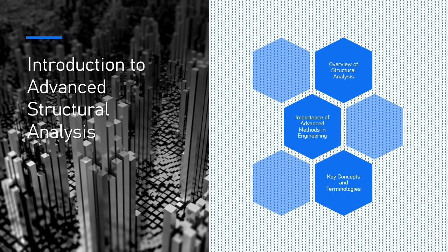Dynamic analysis and response spectrum analysis methods are crucial to understanding how buildings sway, deform, and dissipate energy during an earthquake. Wind and vibration loads. Wind loads on tall buildings, especially in areas subject to extreme weather, need to be analyzed using dynamic load models. Additionally, structures like bridges and high-rise buildings often experience oscillations and vibrations that can affect comfort and safety, which must be analyzed using specialized methods like modal analysis.